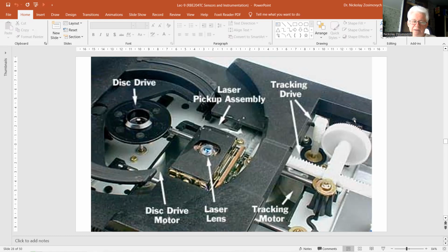In mechatronics and many other applications, it is not always of primary importance to find the exact distance. The detection of an occurrence would be sufficient in many cases: open or closed, presence of a person or object. For this purpose, special optical sensors have been constructed with a wide range of specifications.